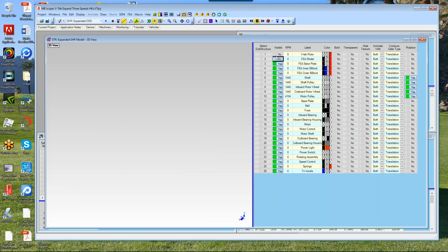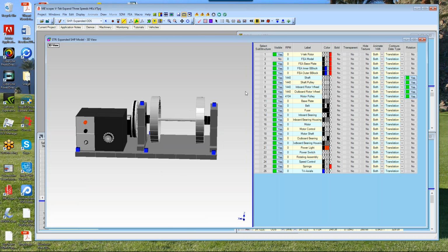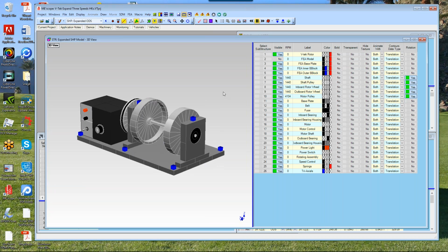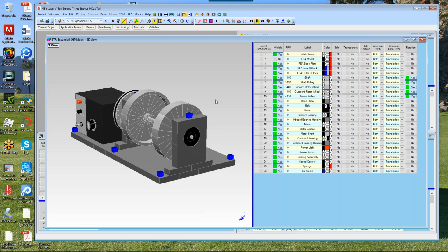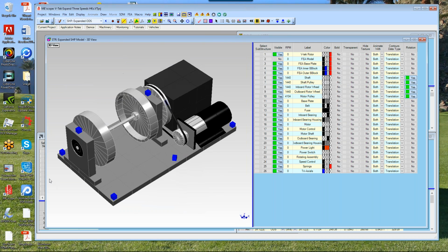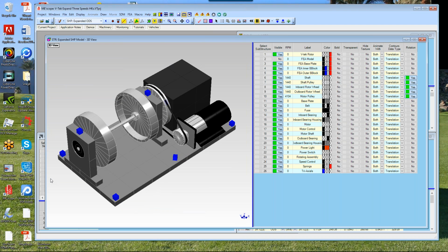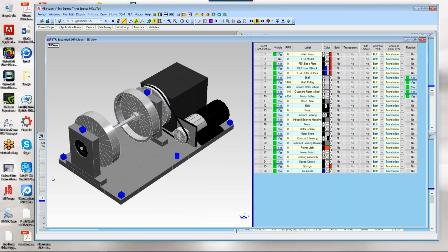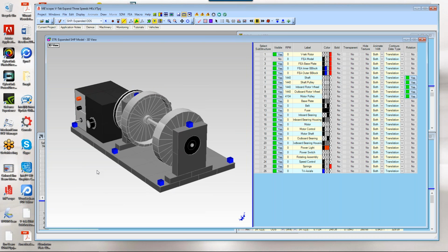So we built the FEA model off of the machine model itself, at least 3 parts of it. And what we're going to say here is that that is the part of the machine that could flex at certain speeds. And we're taking data where each of these blue cubes are. We can get live data off of this machine as it runs and track the ODS, what we call the order-based ODS, first order, or any of the higher orders. Now we've already done that.